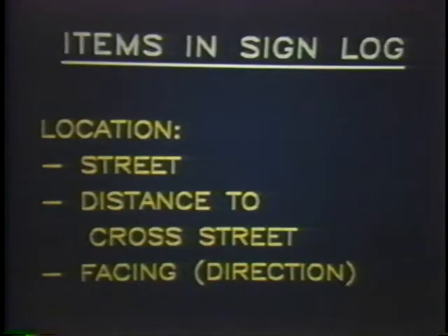As you saw in the video, traffic sign inventory is essential to a well-managed traffic engineering program. A good sign inventory would include the location of the sign and the direction in which the sign faces. The information collected should give a thorough inventory for sign installation and maintenance. 1. The type of sign by the categories defined in the MUTCD. 2.